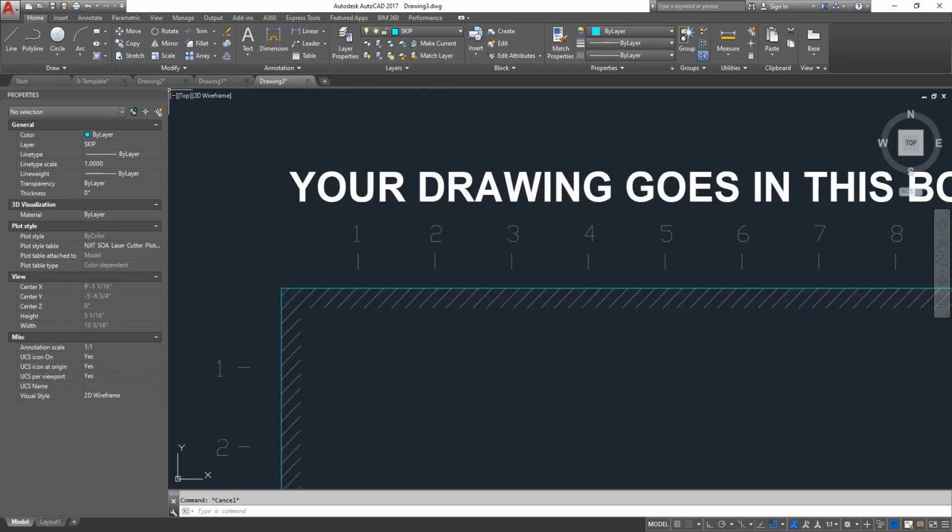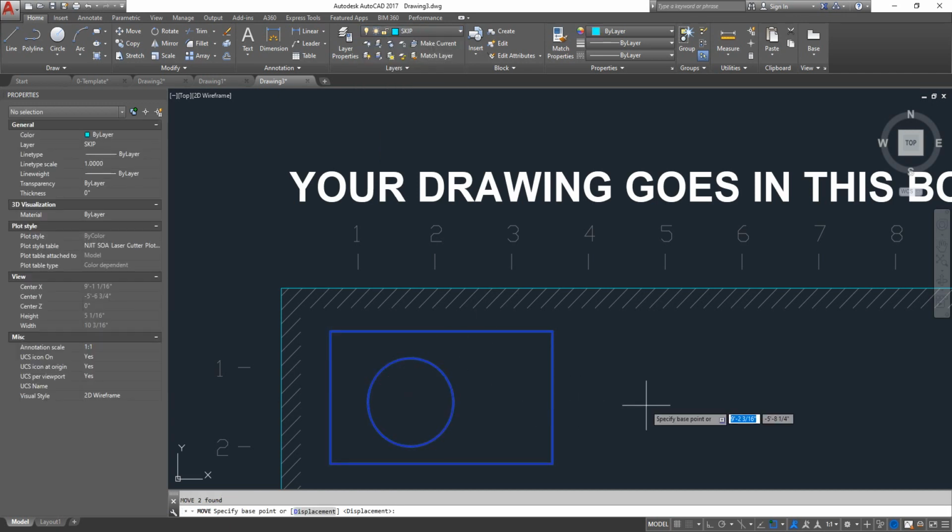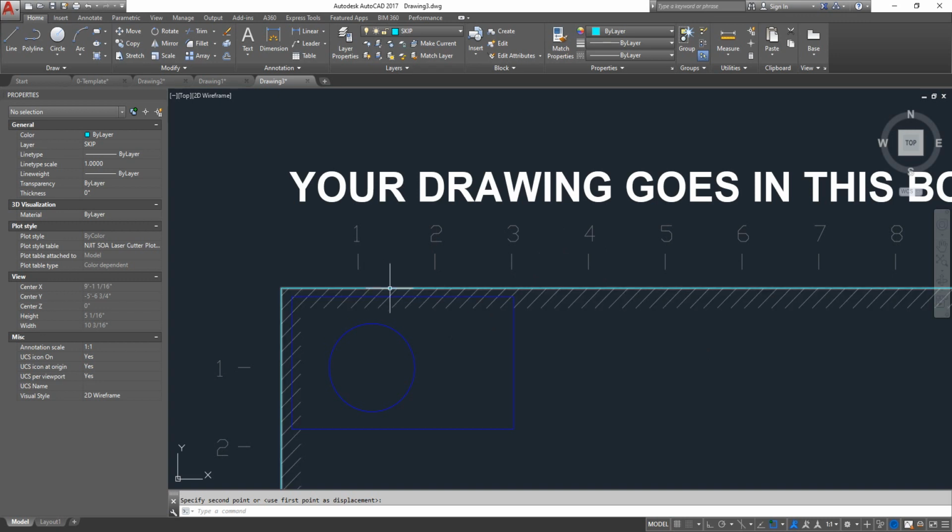So let's say you have this very simple, my favorite test object, a circle within a rectangle. In this location it's fine, but if you move it up into this bleed area, this becomes an issue with the machine. See, the machine uses this area to slow down when it's running across and cutting your file. And if you have a file in this space, you can actually hit the side of the machine and throw off the laser cutter. It'll continue cutting, but let's say it hits the machine on this side and gets thrown off by a 1/4 of an inch.